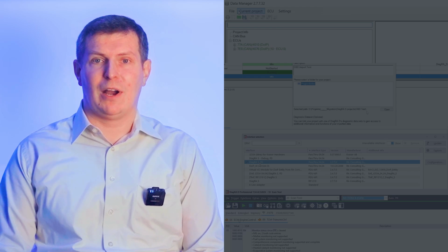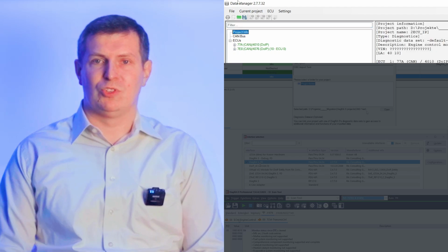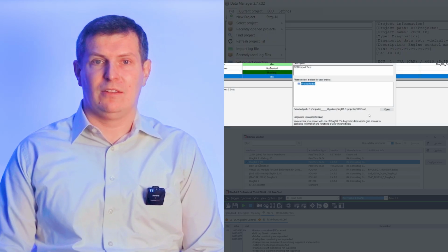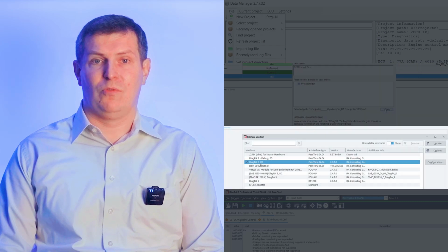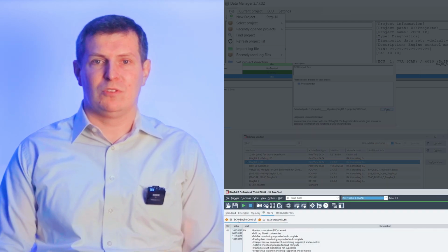Let's summarize today's tutorial. I created a simulation project with DiagRA S. I added the simulation data for OBD communication from trace files recorded by Silver Scan Tool. I configured DiagRA D for OBD communication with DiagRA S and started the simulation of diagnostic communication.